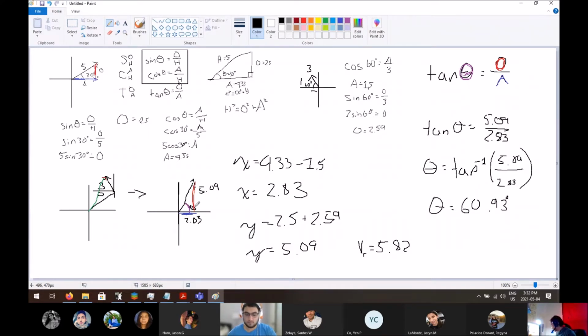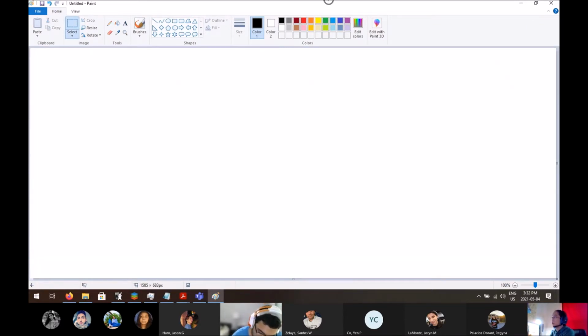Cool. Let's move on to equilibrium. So vectors, very basic mathy stuff. But now we will be talking about beams. You have a beam right here. Let's first go over the difference between all the connections. This connector is a roller. There's only one reaction, in the y direction.